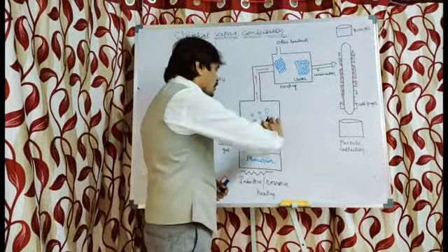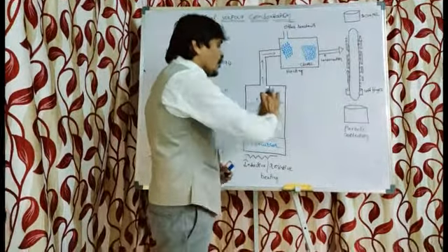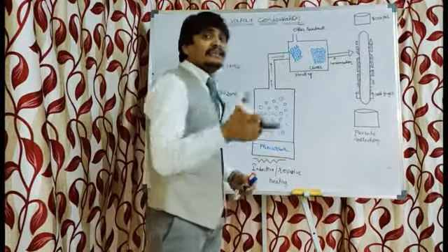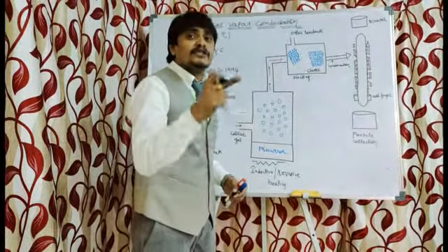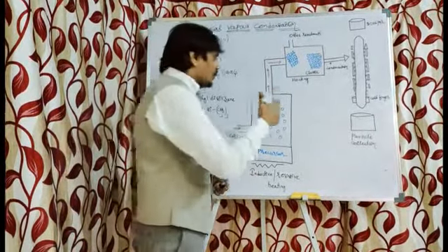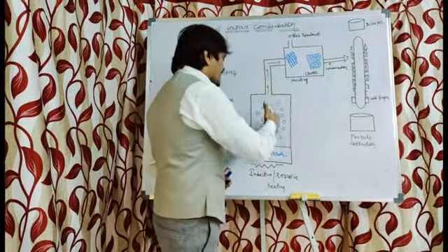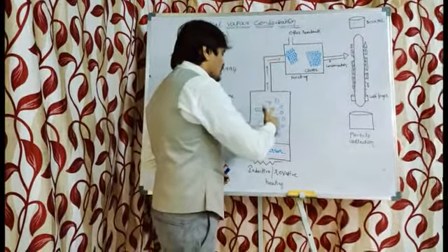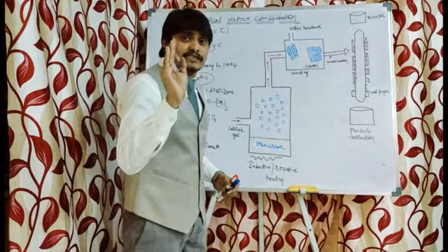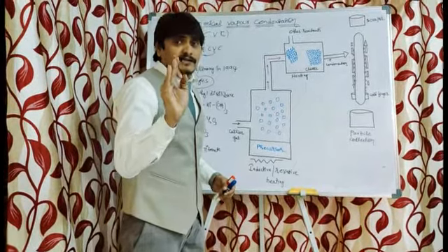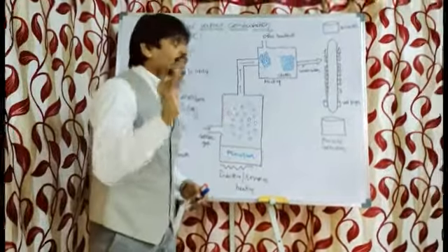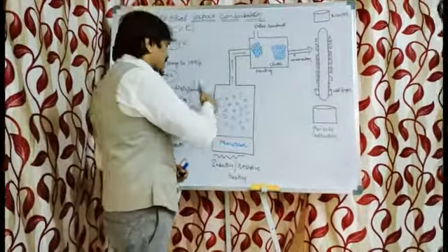And these precursor molecules which have been vaporized will not have enough energy to transfer into the chamber where the condensation of the vaporized molecule takes place. So, as the energy associated with the vaporized precursor molecules is less, there is a need of some molecules which can carry the vaporized precursor molecules into the chamber. That job is being done by the carrier gas.